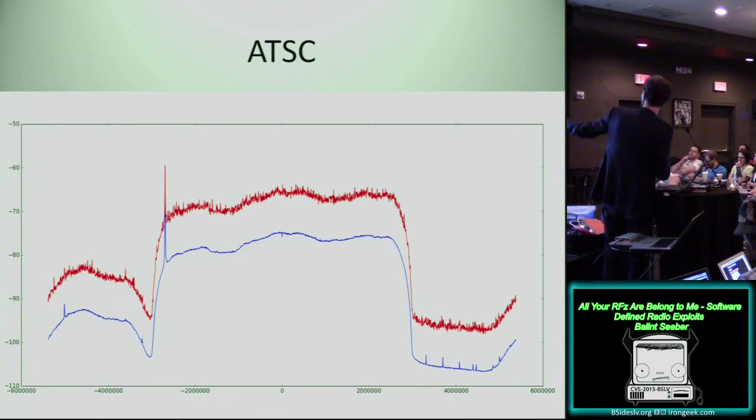You can see that you get this very distinctive shape in the spectrum that indicates that it's digital TV. It has this flattish shape, but then you have the spike, and that's known as the pilot tone. You can tell you're looking at digital TV because on the left-hand side you'll always have this pilot tone. It's just due to the way they do the modulation.